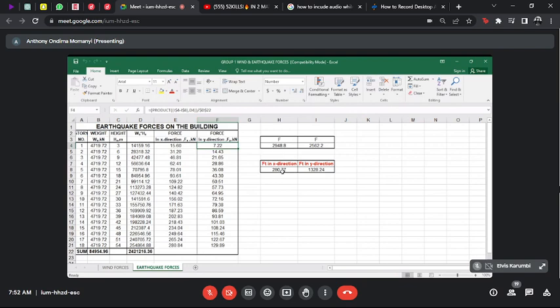You see where H4 is 2948.8. So if your distribution is correct, then the total amount of force at the bottom, including the top floor force, which is 280.77, if you sum all that, should give you 2948.8. That's one of the easiest checks to check whether your calculation is correct. All right.